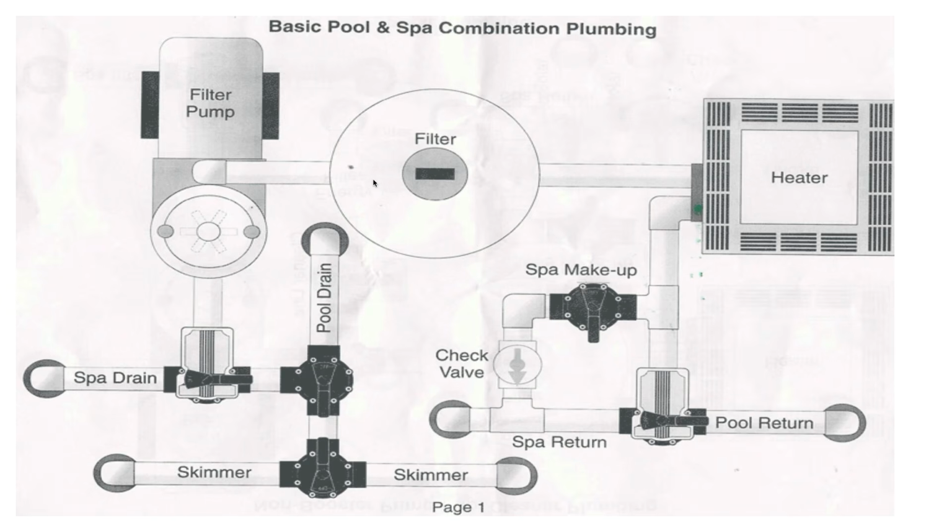And then here we have our pool heater. And this is another common version of a bypass on the pool heater. If you see the way that it is set up right here, it's turned to be open so the water can flow right through the bypass. And you'd want it turned closed so the water is forced through the heater. Actually, this one isn't a bypass, is it?